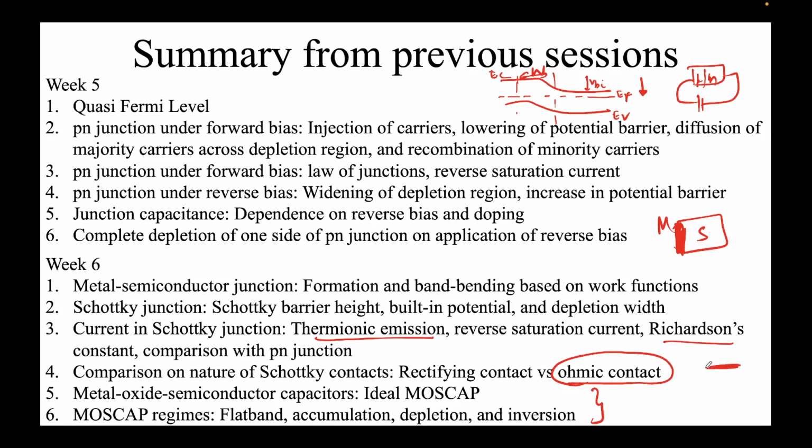Just to clarify again, so this is your metal pad, to which we apply some potential Vg. This is some oxide. If it's silicon, usually it's silicon oxide, and here is your semiconductor. So metal, oxide, and semiconductor. This is a capacitor. The other terminal can be on the semiconductor itself. Let's say this is the other terminal, which we usually ground. This is also known as the body, by the way. So we saw 4 regimes.